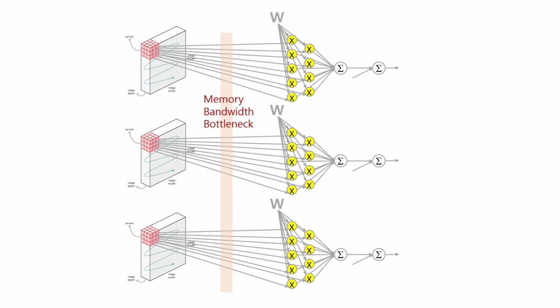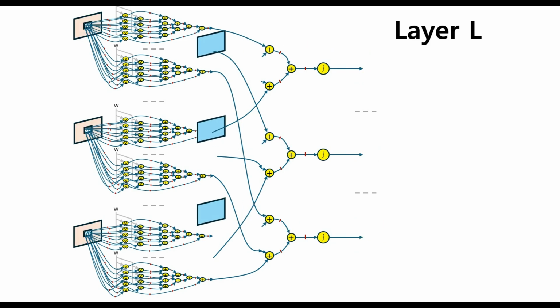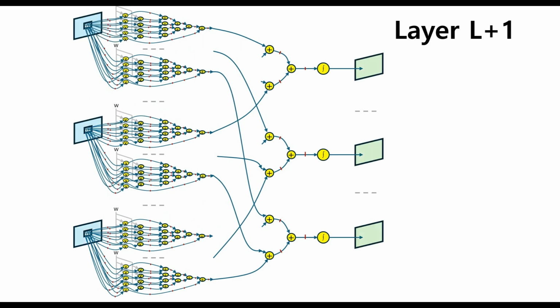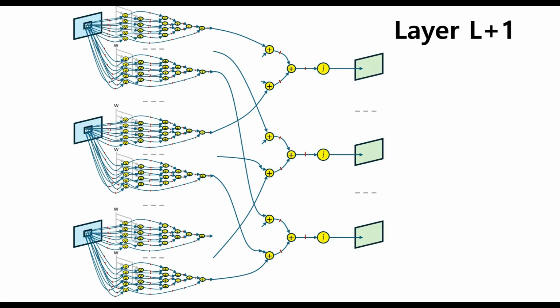Third, the multiplier input must be provided without interruption even when the convolutional layer is switched. To do this, the computational result of one convolutional layer must be immediately available as input data for the next layer. If additional memory operations are required in the middle, data cannot be supplied to the multipliers during that time. So the multiplication circuit must temporarily stop calculating, which results in a decrease in the efficiency of the entire system.